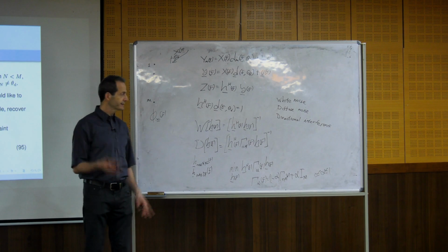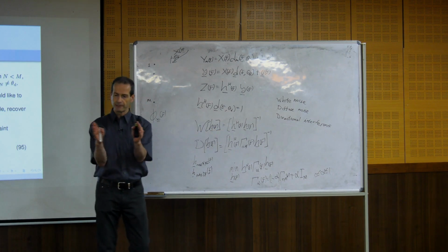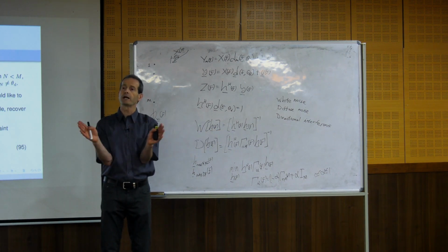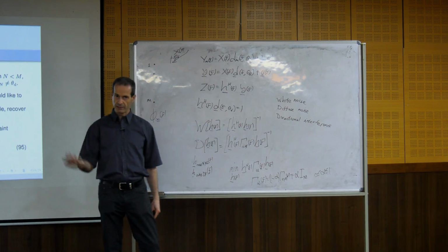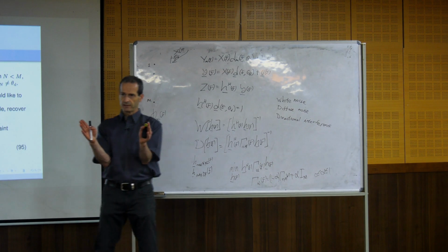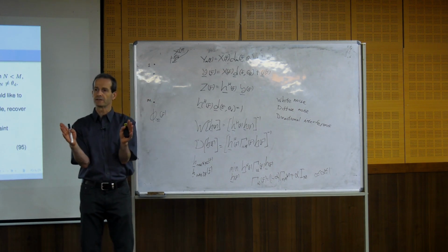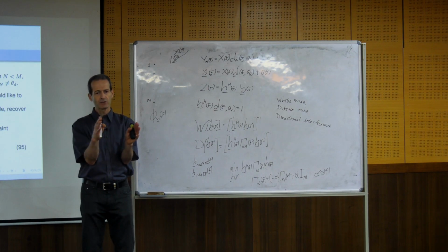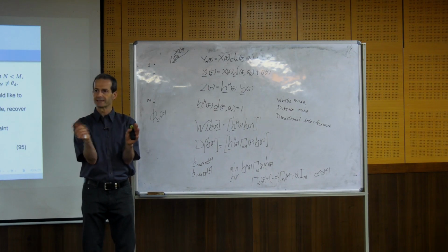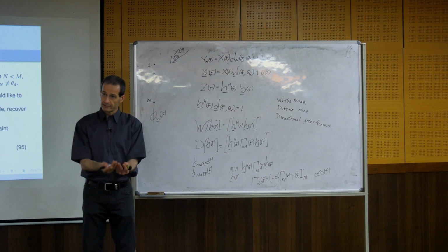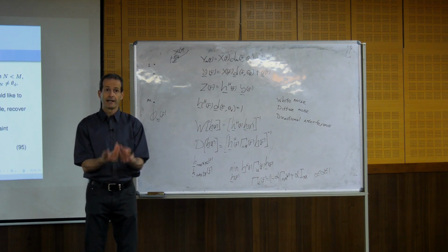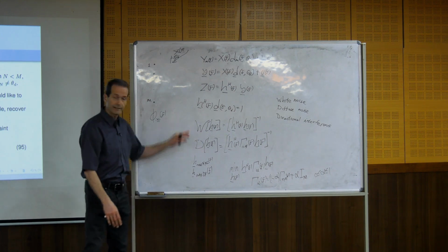So I will design the beamformer such that the beam pattern, the main beam, will be wider. I can add a requirement that the width of the main beam will be wider. Why? Because if I don't know theta d exactly, I don't want it to result in significant degradation, suppression of the desired signal. So I add an additional requirement, which will degrade the performance.